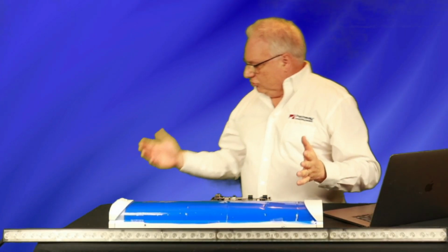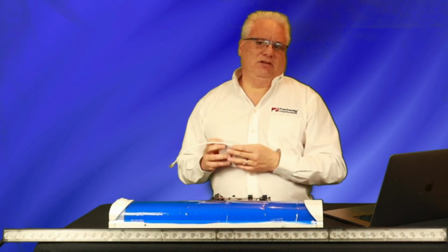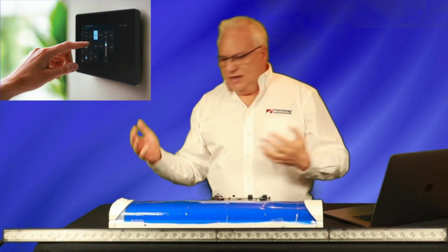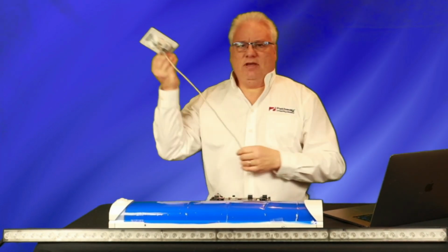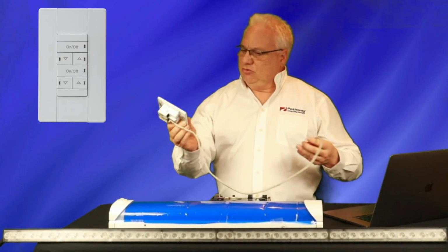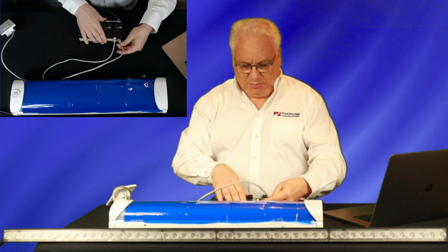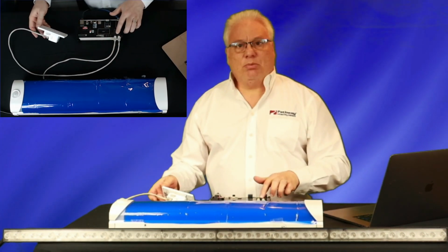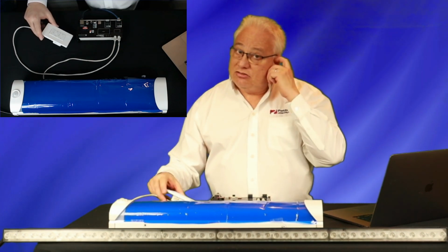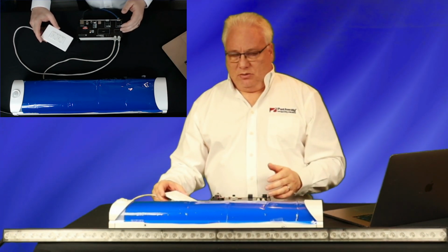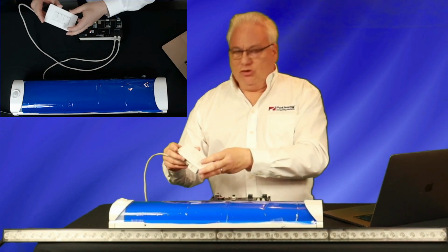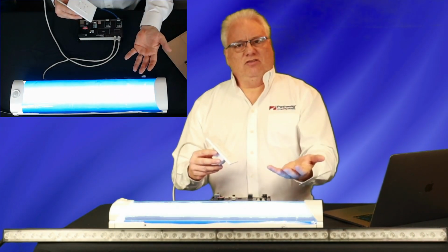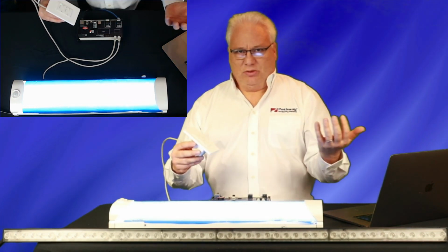Now, I can control this with any nLight device like an NCM or NTS, but I have an nPODMA here. This one is a 2P, so I will plug that into the other side of my nLight port, and the nLight port is supplying 40 milliamps of power. And after it's done the negotiation, I can just press the on button here and we get intensity on channel 1. This is nothing new.